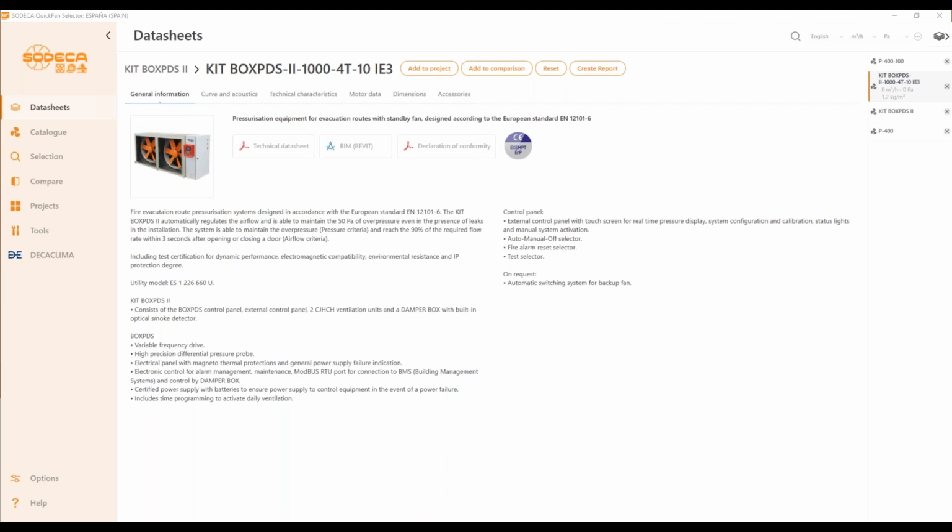For performance-based design, you can follow, for instance, ISO 23932 Part 1. There you have the methodology to carry out performance-based design, but the performance-based design is something else than just a CFD simulation.